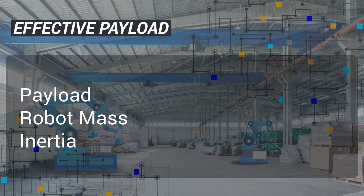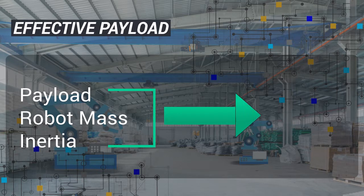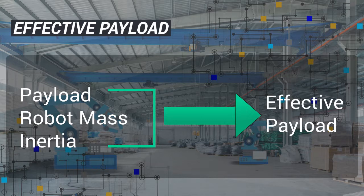The effective payload includes the actual payload, the mass of the tool or end effector attached to the robot to carry the payload, the inertia of the robot computed as a mass at the radius of impact, and the forward reflected inertia of the motor and drivetrain computed as a mass at the radius of impact.